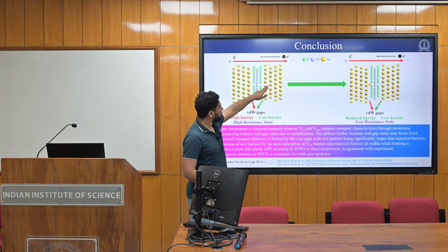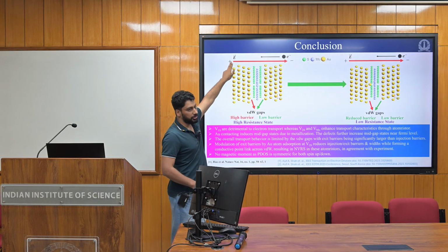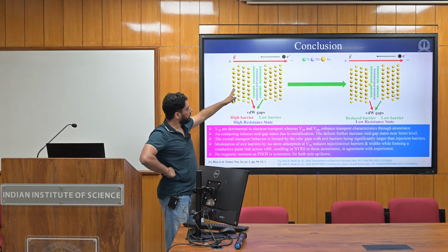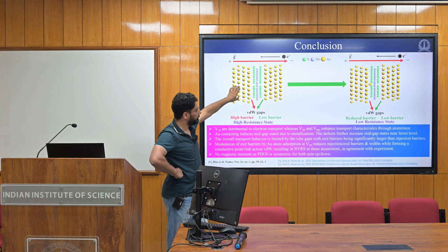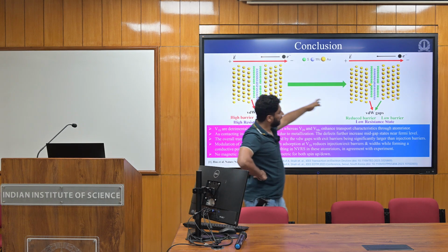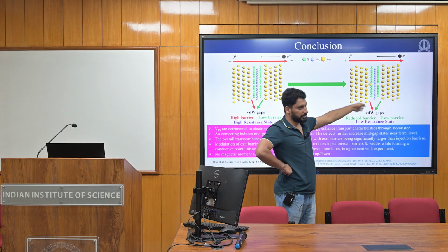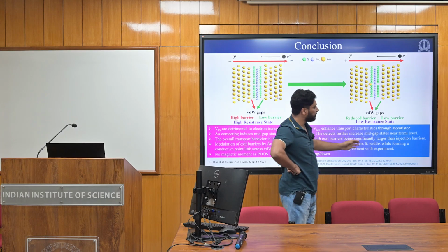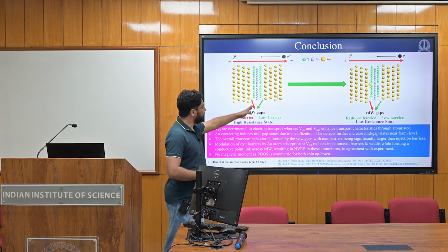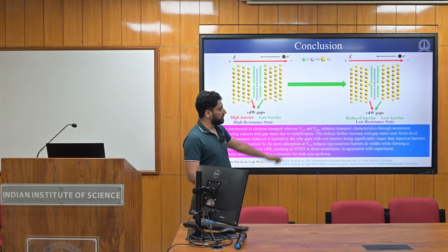So the electrons will follow the tunneling path through this to MoS2 and then back to this. But once you apply a positive voltage, the gold atoms from this gold electrode migrate and adsorb at the disulfur vacancies in this Atomristor, and because of that, this exit barrier drops very significantly compared to this one, and that's what results in the low resistance state of this